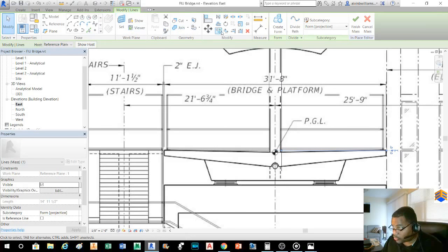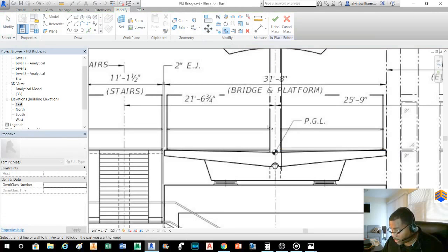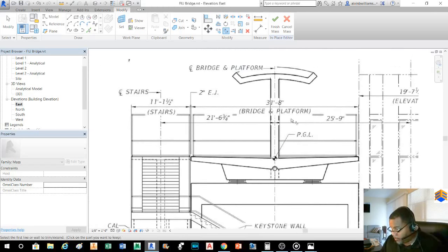So I'm going to go to the trim extend tool again. You want to click on the sides that you want to keep. Like if I clicked here and then clicked this line, it would cut away this side of the line and just make a 90-degree corner here. But since I'm clicking over on this side of the line and then clicking this one, it's going to get rid of this, like so. All right.